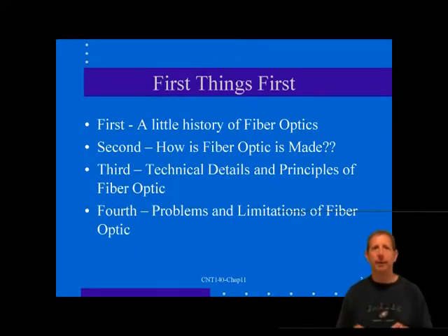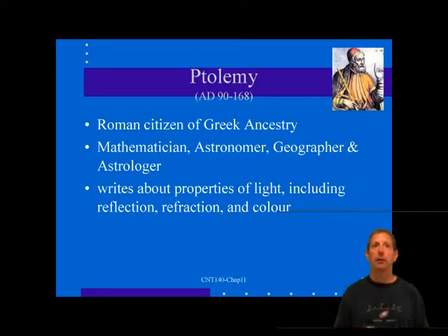So let's look at the fiber optic basics. Before we delve into the LAN applications, let's review the basics of fiber technology. We need to understand how optical transmission works and what the key terms and parameters are. The phenomenon of the transmission of light through fiber optic media comes from the optical principles of refraction and reflection.